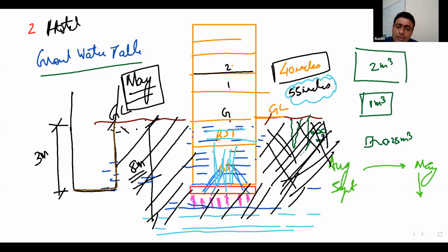Now, what had happened was that these structural designers were from Mumbai, I think. So they were unaware of these issues, and they just looked at the report of groundwater table. That groundwater testing was carried out in the month of May. So they designed their basement slab and raft without considering uplifts and without considering any buoyancy, and that was the problem. In Indore, we design for uplift and we also investigate the swelling pressures.